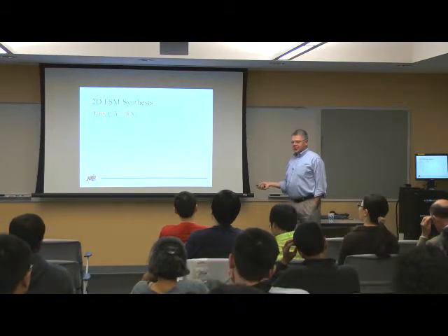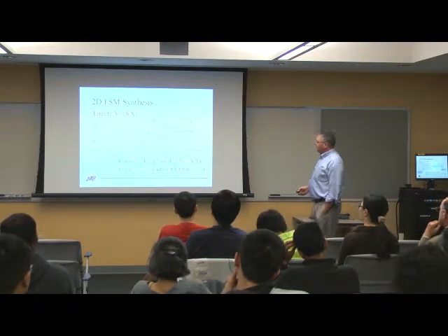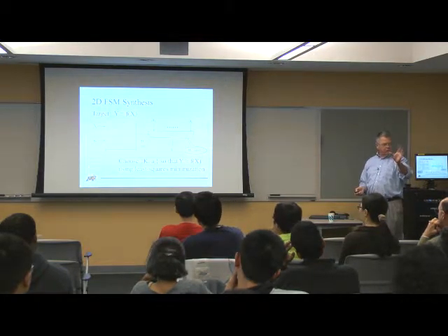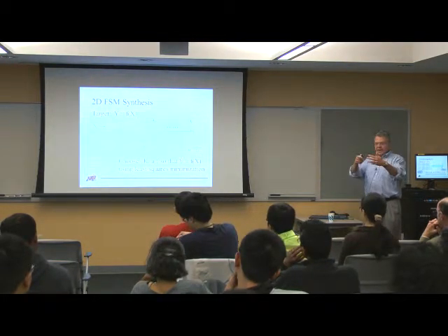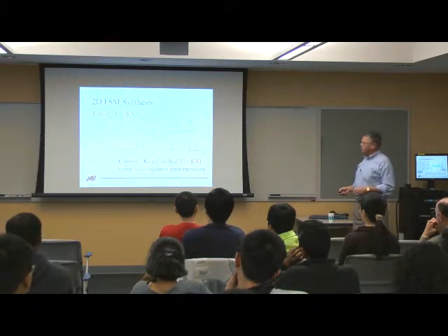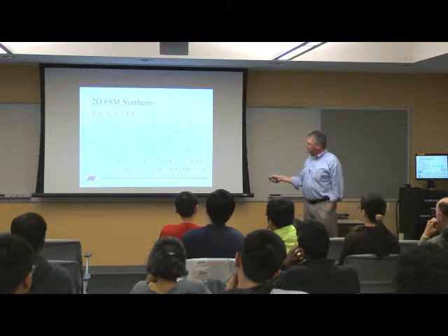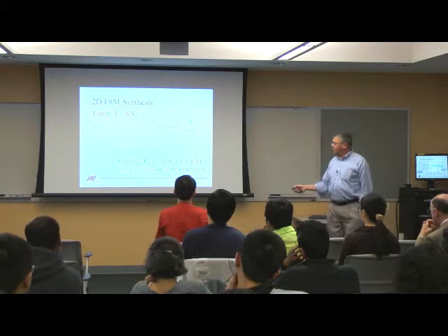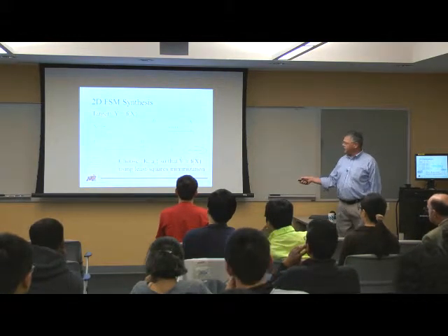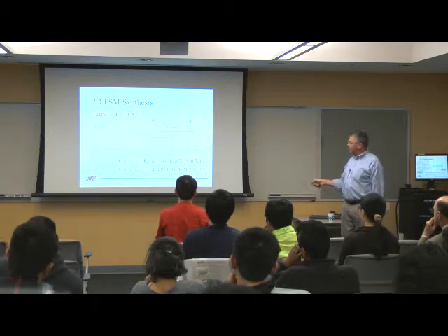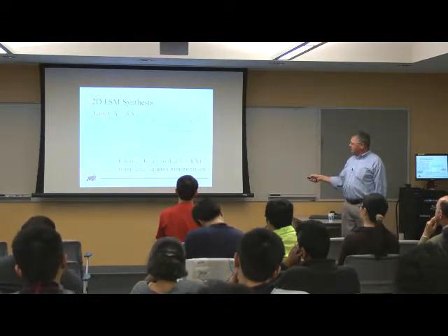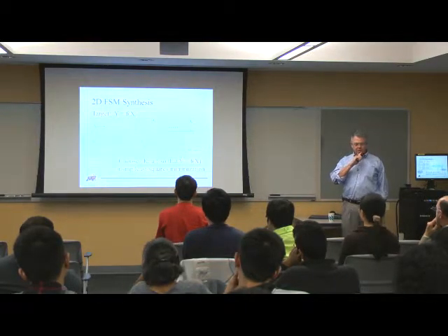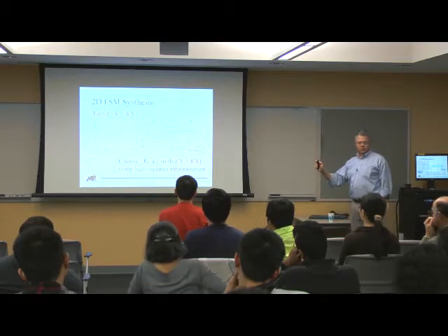All right. So how do I synthesize things in general from this? Well, this is what the circuit looks like. If you think back to that generalized multiplexer that I showed you with the inputs, the adder, and the multiplexer, this is the equivalent circuit for the finite state machine, where I have this two-dimensional finite state machine here, which remember is just registers and some logic. I have two inputs, x and k, where k is a parameter that I choose as the designer. I have m bits coming out for the state. And then I have this multiplexer, and I'm going to select these different coefficients based on what state I'm in. So it's very much like this Bernstein implementation.